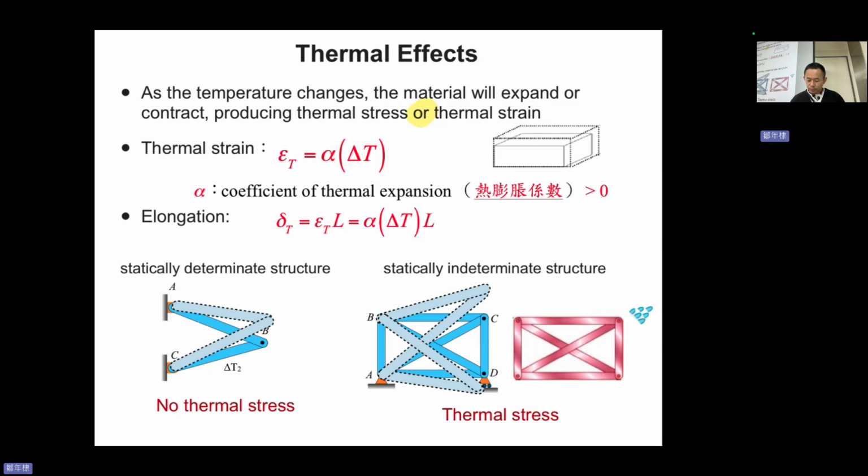You can see that if the material is here, and you increase the temperature, and both of them elongate, become longer, and both of them increase in length, but freely. So they have thermal strain, but the state is stress-free. No stress inside this, no thermal stress.